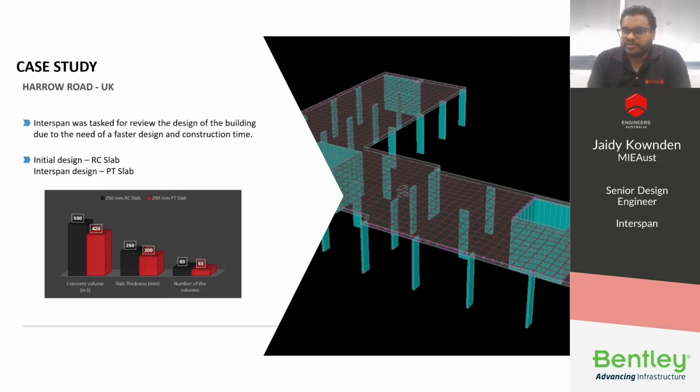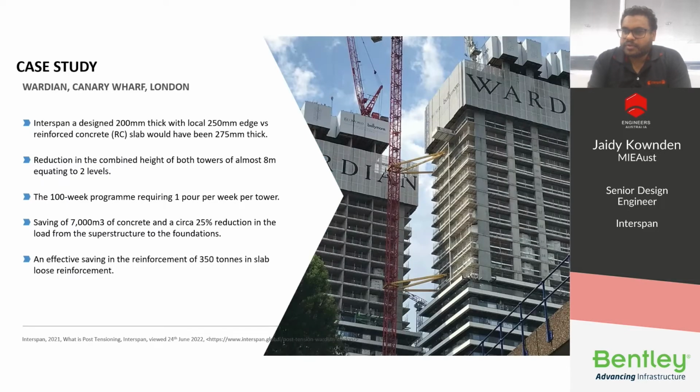The next project that I would like to talk about is the Wardian in Canary Wharf, still in London. We have designed a 200 mil thick slab with local 250 edges versus a concrete RC slab of 275 thick. The reduction in the combined height of the two towers is almost 8 meters, equating to 2 levels.